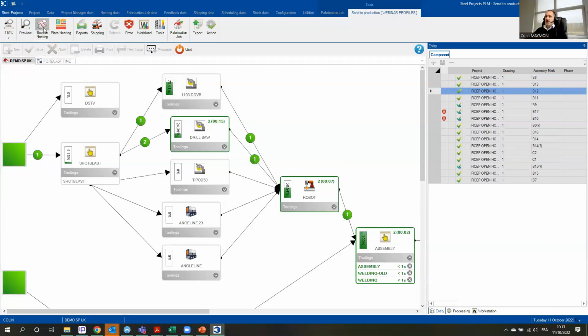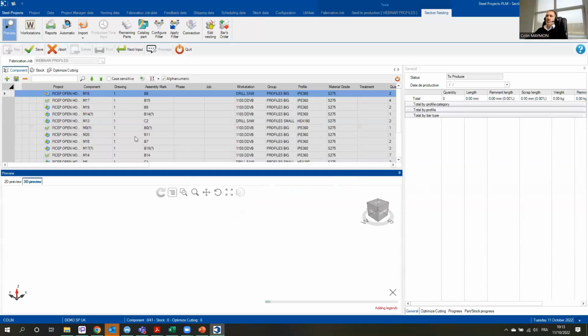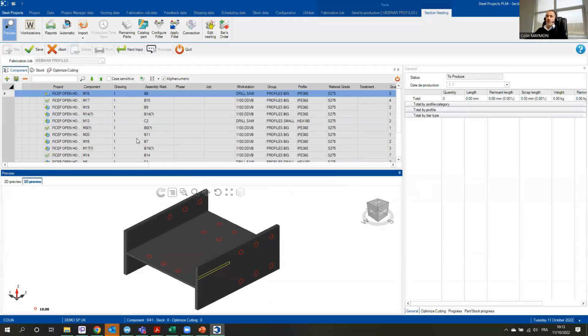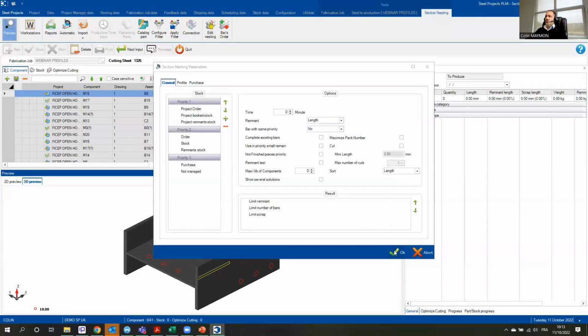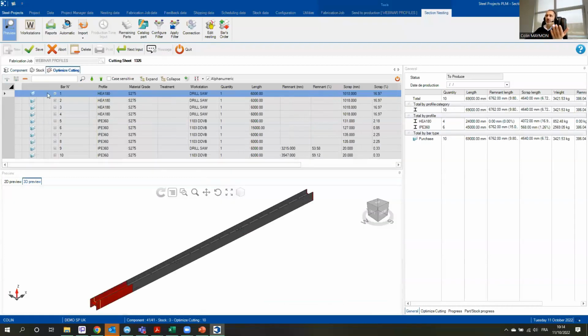Now let's make a nesting. I don't speak about the nesting today. We did make a webinar on the nesting that you can retrieve on our YouTube channel or on our website. I'm just making a quick nesting in order to show you the rest. When the nesting is done, the production will go through the virtual layout again, but not as a component, but as a bar, okay? And we will have time estimation per bar and not per component anymore.